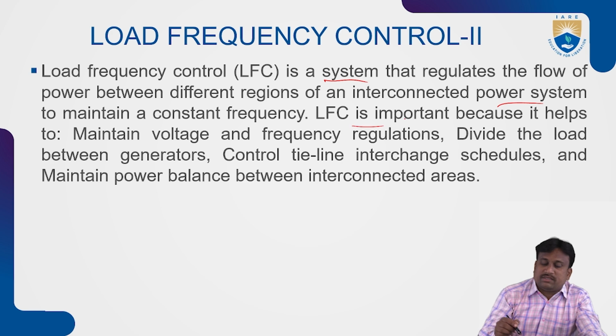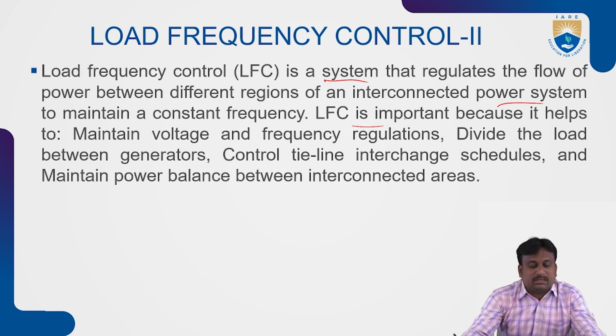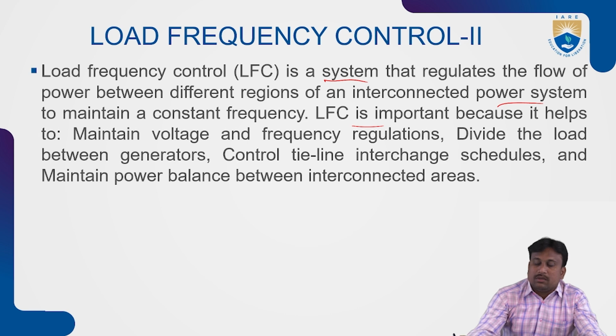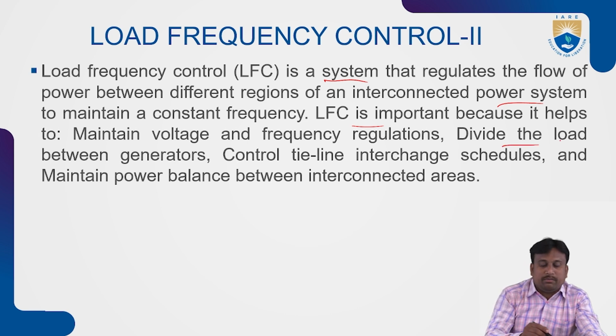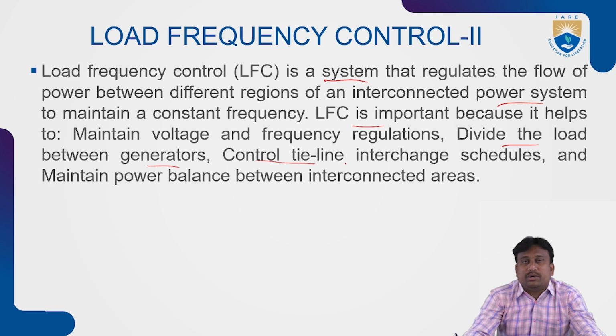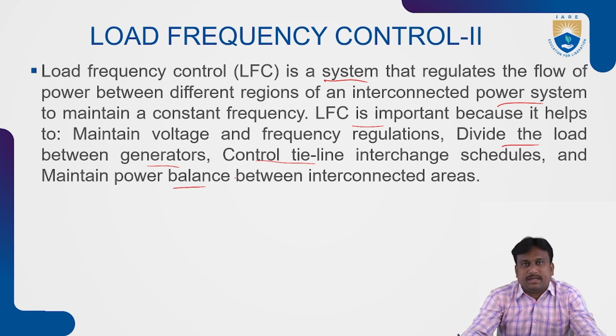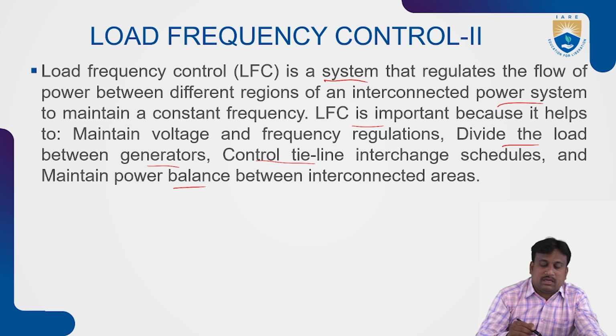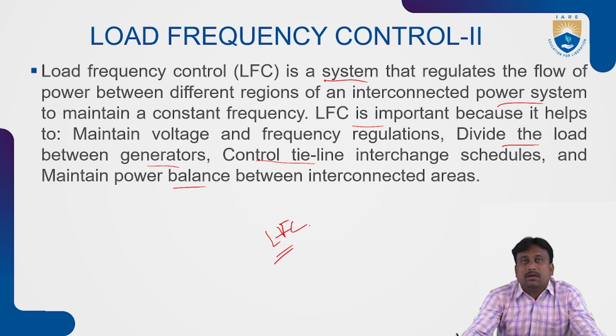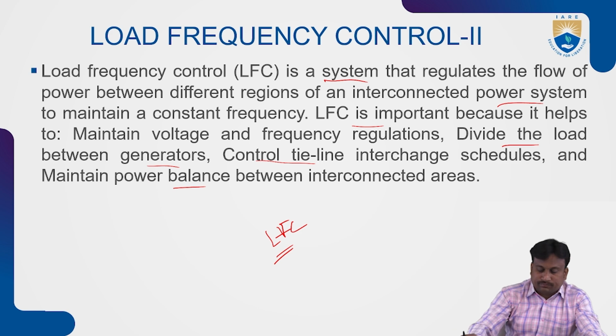Load frequency control is important because it helps to maintain voltage and frequency regulation. It divides the load between the generators, controls tie line interchange schedules, and maintains the power balance between the interconnected areas. Likewise LFC takes place, to maintain a constant frequency.